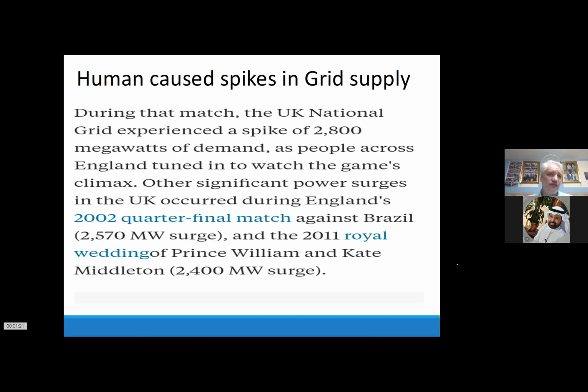So if you use, for example, all the strings on the top, the output would be all 75 degrees. And then you go to the bottom further on, that means you have individual strings with 50, 60, 70, and 75 degrees differences. If you couple it this way, you get a much better output, because those individual DC combiner boxes or these individual strings work much better with similar outputs.